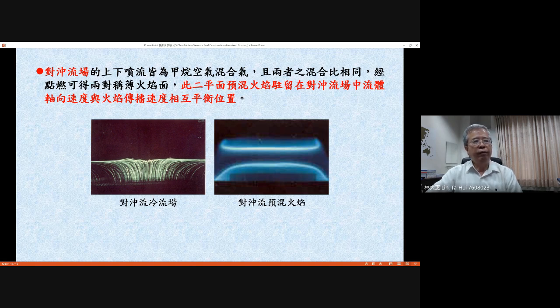But when you ignite it for two identical premixtures from upper and lower burners, you will see a double flame, okay, parallel planar premixed flames sitting together. There is some edge effect because for the experimental system we have a suction exhaust system. We need to suck out all the products and prevent the so-called buoyancy effect. Those suctions are coming from the downstream, from the lower burner. Then you can see the flame bend down. This is due to the suction on the edge of the lower burner.